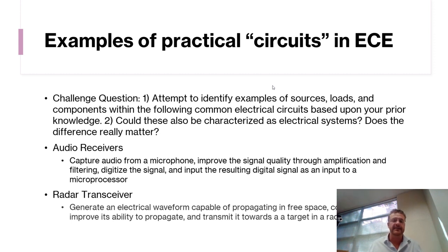Maybe I want to do some processing to clean up my signal a bit, and maybe I need to amplify it as well before I even worry about this concept of digitization. That kind of processing, where you clean up a signal and amplify it, is often known as signal conditioning. So that's going to involve things like filters and amplifiers, and hopefully those are terms that you've heard before. And then if I want to post this online so you can watch it whenever you want, I'm going to need to make it in a form that's compatible with computers. That process is known as digitization.